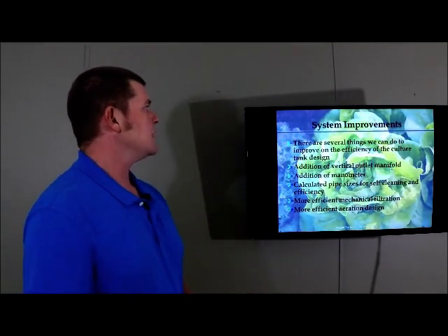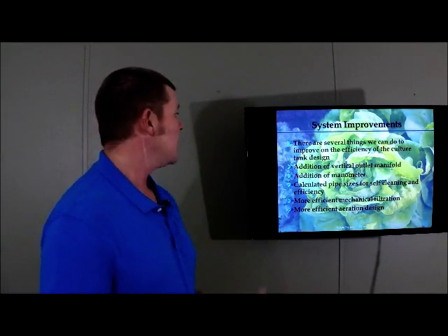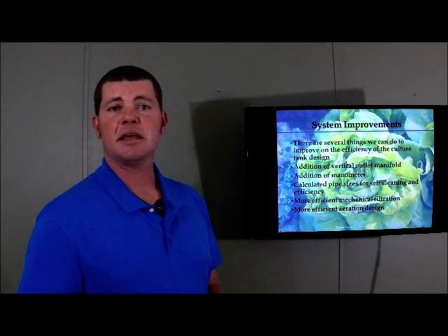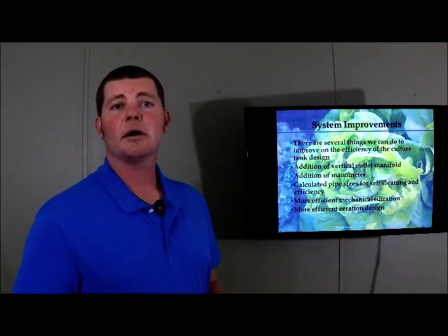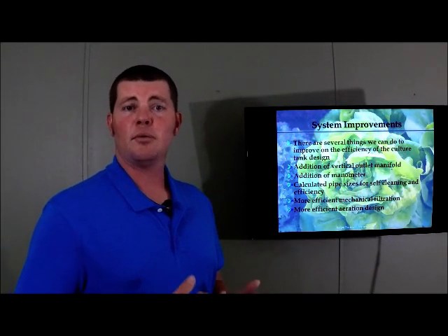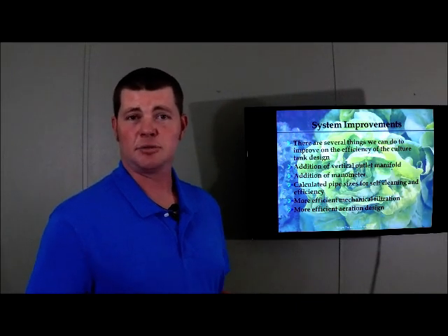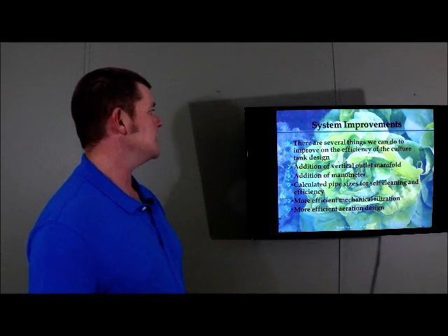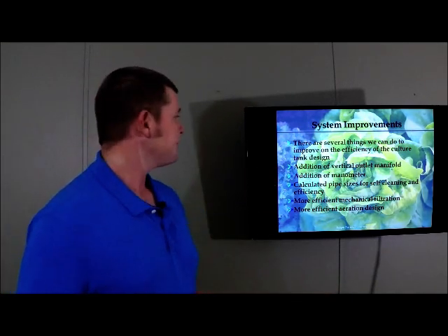So, some system improvements. There are several things we can do to improve the efficiency of the culture tank design. The addition of a vertical outlet manifold in those 2,000-gallon tanks would really help to move the waste out of the tanks quicker, giving you better water quality, lower ammonia, faster removal of solids out of the system, and actually higher oxygen levels because we don't have those organics degrading in the water column. So all positives from a simple addition of maybe a $30 piece of plumbing.